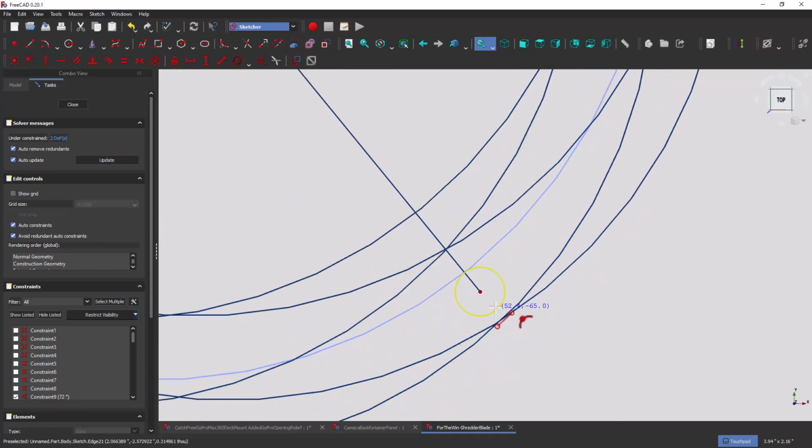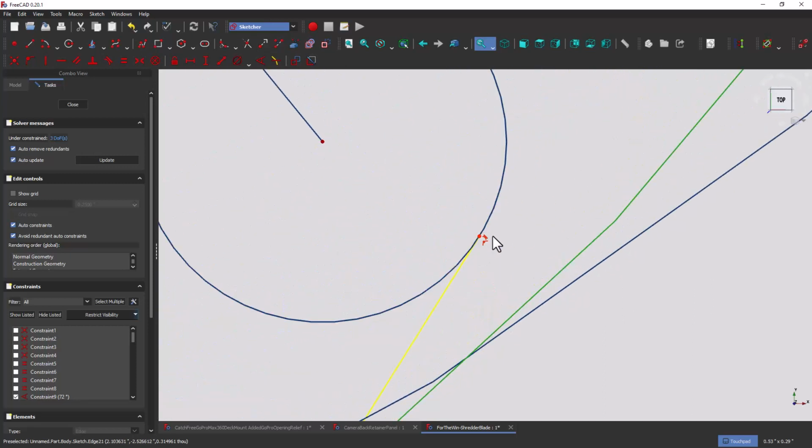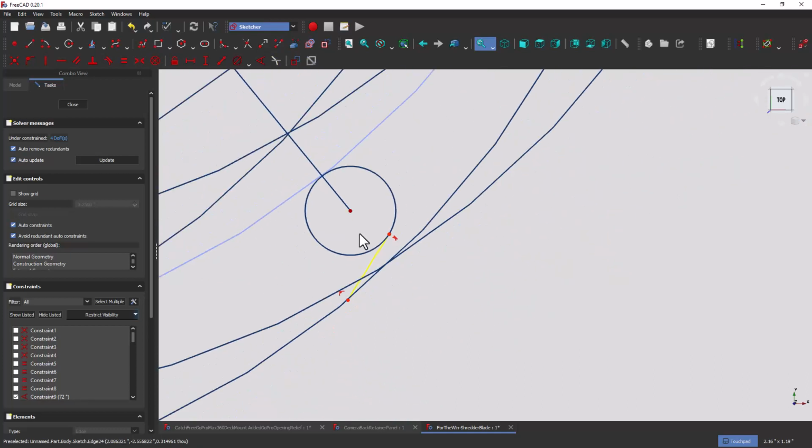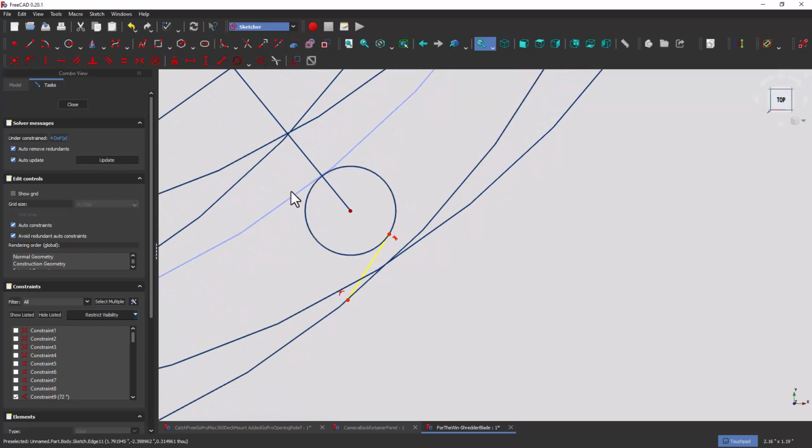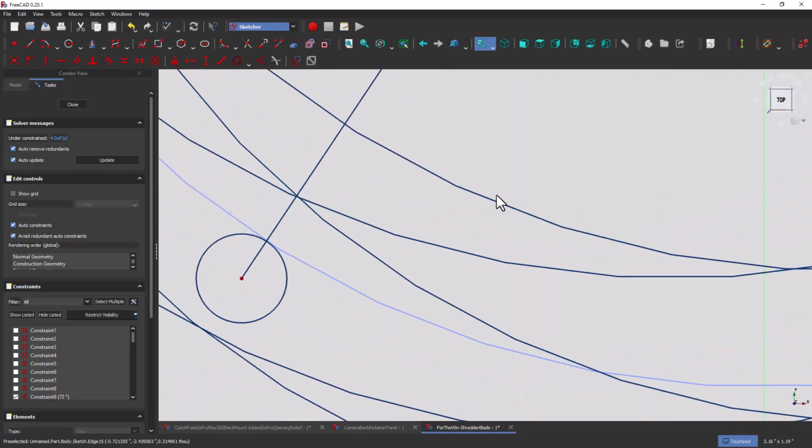See what happens is if I do it at the right angle, it'll automatically make it tangent. And it did. It not only added in tangent, but it's adding in that redundant, and that's what gives us troubles. You only need one of these. It should be auto-deleting that, but it's not. Delete. So there you go with FreeCAD. I don't know if it's part of a legit design process or not, but it doesn't seem like it to me. But boy, there's just so much going on under the covers here that the fact that it works at all makes me happy.